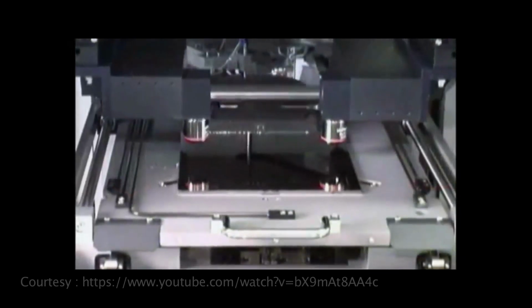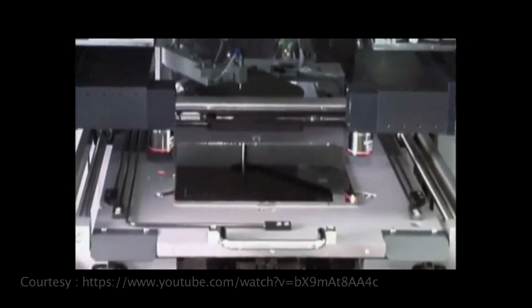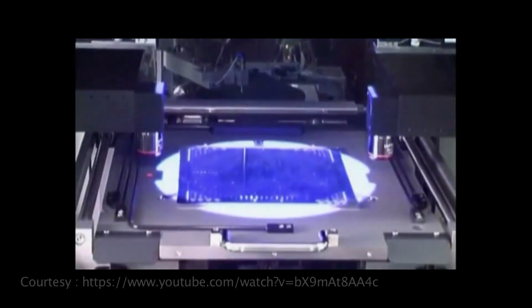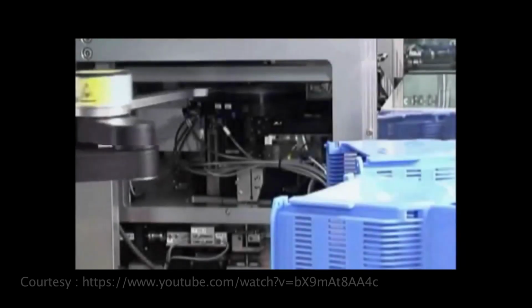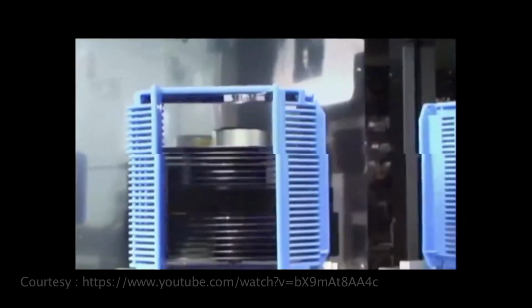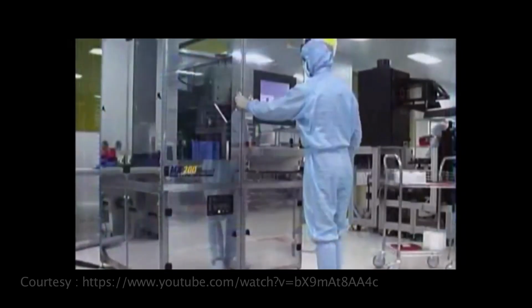In thin resists, it achieves a resolution of 3 microns in proximity mode and a sub-micron resolution in contact printing. A microscope for bottom side alignment is optionally available. It can process substrates with thicknesses of up to 4 millimeters.